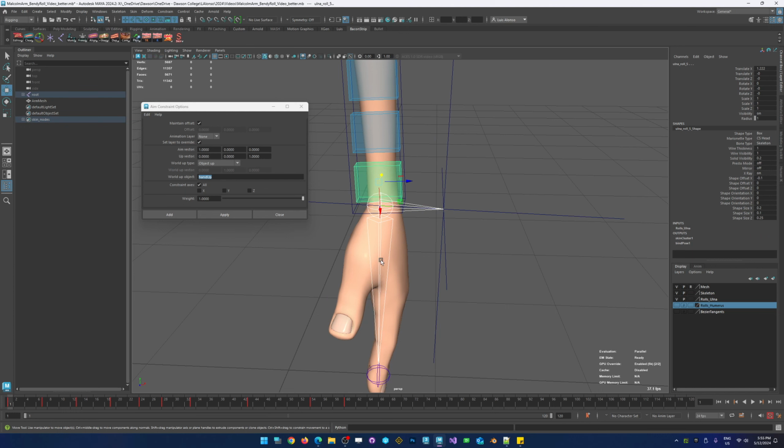All right, because of the order of selection, we've basically told the tool the first thing I selected was the object I'm going to aim at. Then this is the thing that's going to be modified by that. And then I'm going to use an object up for figuring out where that is. And by clicking it, look at that. The decimals are really tiny errors. So we did a good job of setting everything up so that we didn't even need the maintain offset. It would have been fine.